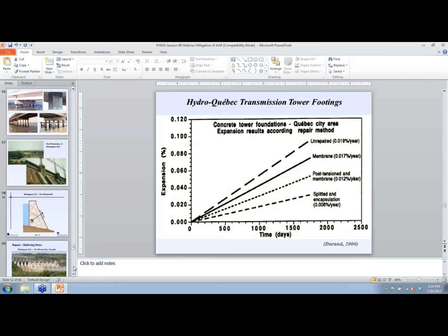Okay, well enough. And the next question is, what is the best method to check a concrete that is suspected to have a reactive aggregate but does not show any external signs of ASR? Yeah, I'll defer that one to Ben, because I think it's going to fall in the hands of a petrographer. Yeah, this is very much the case, Kevin. I would say that probably the best thing to do is to grab a core, do a petrographic examination. To complement that, some expansion tests can be done on the cores to determine if there is any potential for expansion.